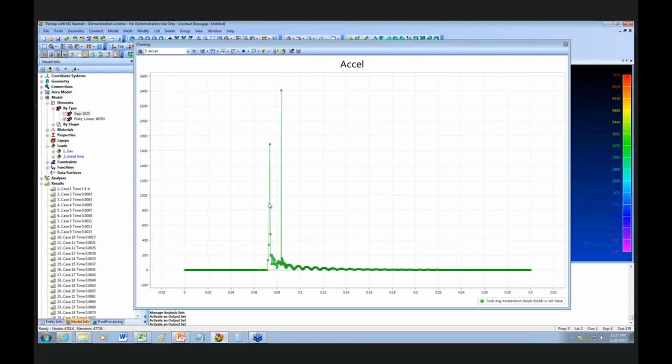And why I say it's not realistic is because the contact is not really tied together. There's slippage in there. There's some friction. But I think you will see a little bit higher stress due to contact. And another thing here is at this point we could come to the conclusion that the transient and the nonlinear are probably giving fairly close results, and they are. We're seeing a little bit higher stresses with the nonlinear, and so it's doing a good job. And why it's doing a good job is that the box never breaks contact with the structure.